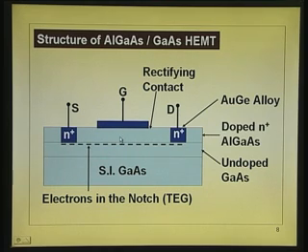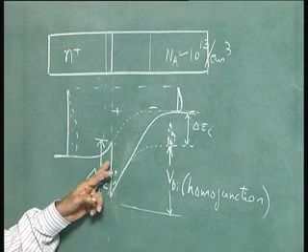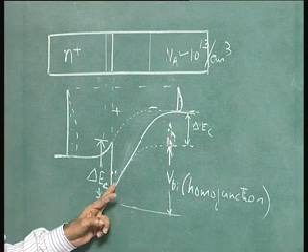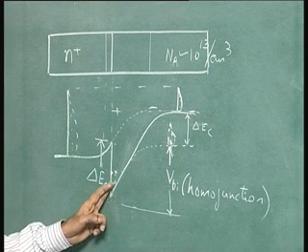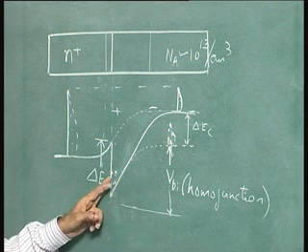But these electrons which are present, they brush aside those dopants. The dopants are just close here. So, if I have only GaAs heavily doped right up to this point, then these electrons which are present are in close contact with the dopants.